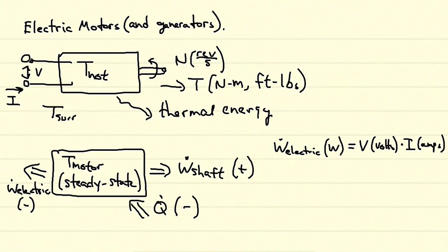And that's nothing more than a variation of Ohm's law. If you remember, Ohm's law is a relationship among current, voltage, and resistance. We can essentially modify that so that we get it in terms of power, in which case power is simply voltage times current.